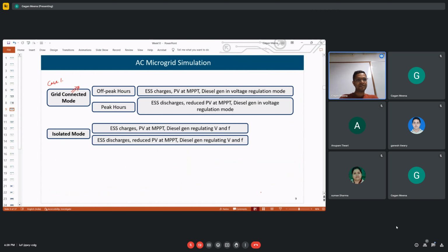improving voltage profile. Because we see at the far end of the distribution system, the voltage reduces, voltage dips. So to boost the voltage, we use them. So that is for improving the voltage profile. Then at the point of interconnection, power factor correction is used.